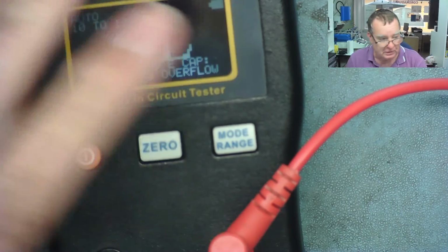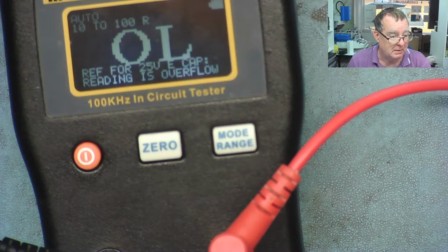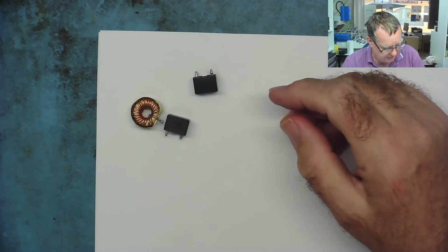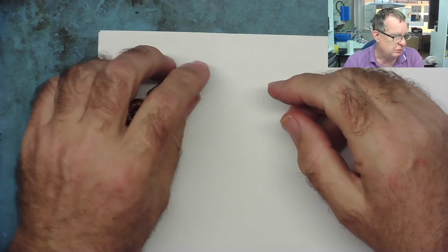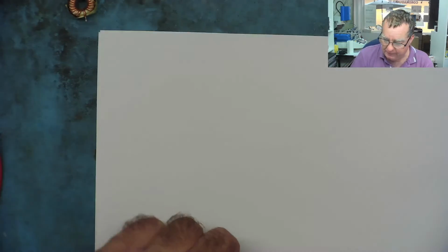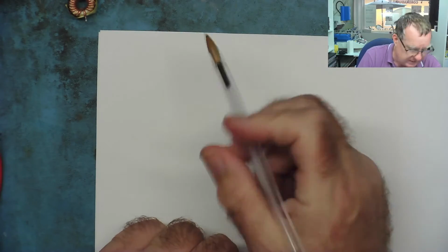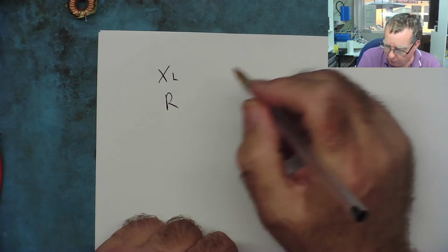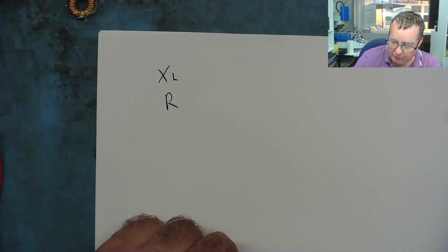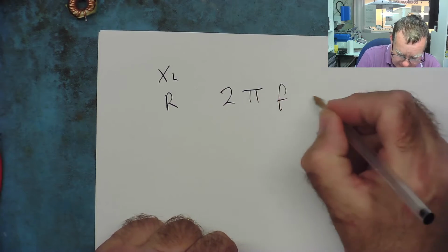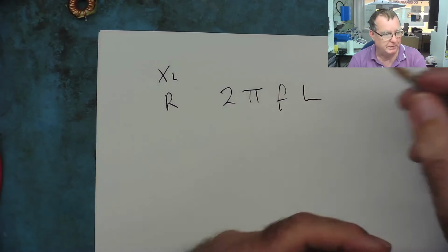And there's a formula to do this, and I'm just going to show it to you now. The resistance I read of an inductor depends on the frequency of the signal that I'm sending through the inductor. It's actually called reactance, or if you like, inductance. So there is a formula, and the formula is this. The symbol for reactance is XL. But for our purposes, we can call it R, the resistance, okay? And the formula is 2 pi F L, which looks very complicated, but I'm going to make it very simple for you.